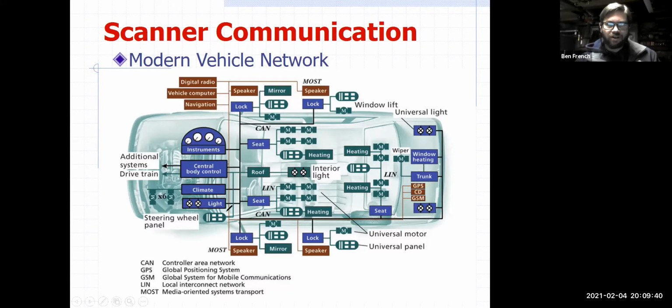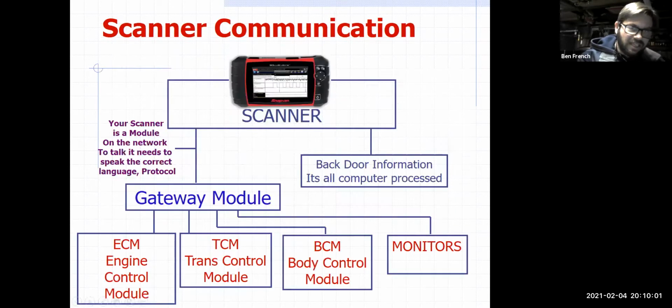So if your car's computer network gets shorted down and these computers can't talk to each other, guess what? The car's not going to start, or it can do all kinds of other weird things as well. So that's what that was about. And stuff that you wouldn't think is related is now related on a modern car because of the way everything's networked together.